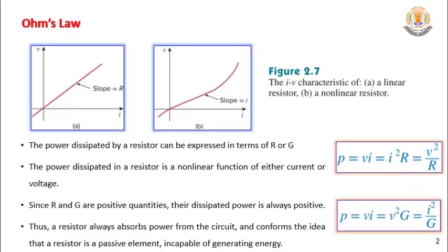Regarding linearity, we agreed Ohm's law will be used for linear circuits. What's meant by linear circuit? This means the exponent here is 1. Linear. Clear? This means the relation between V and I will be a straight line, and the slope is R. Do you agree? A straight line passing through the origin. Sometimes you have some elements where the relation between voltage and current is non-linear. Non-linear. And this will be studied in electronics. So in our course, we are going to study linear circuits. Clear?